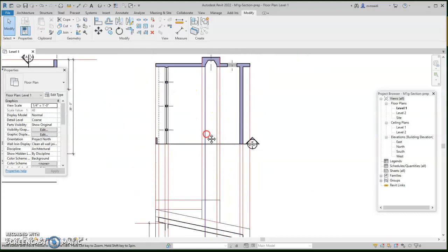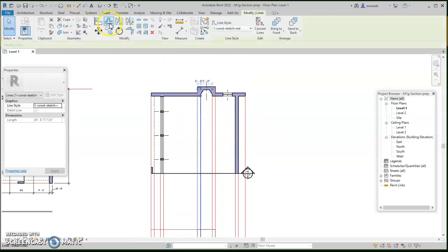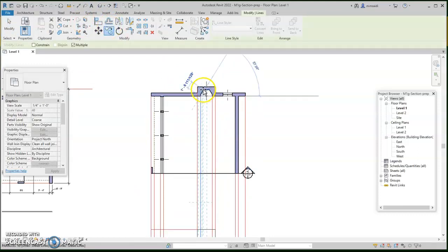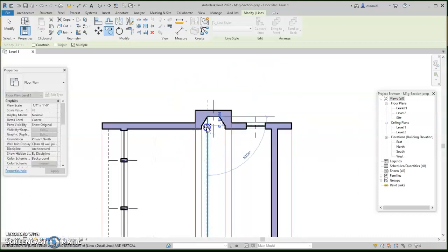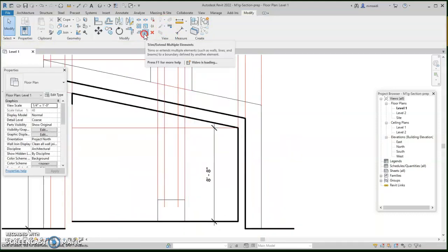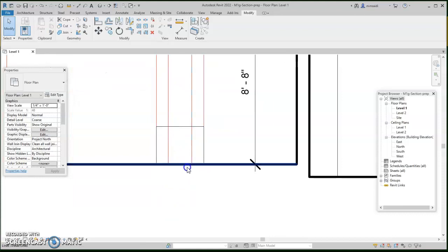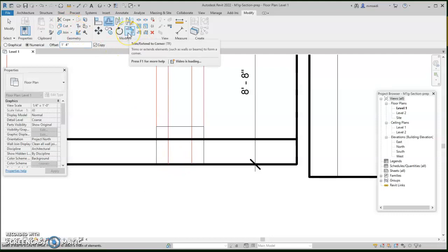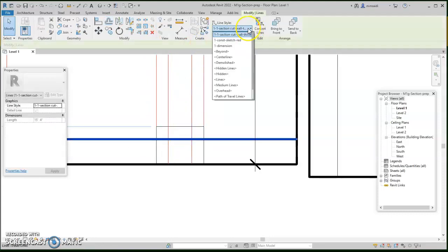Now I'm going to take another line, and I'm going to take this line, copy. From this junction, I'm going to go to this intersection. And might as well put it on the opposite intersection. That's the inside of my fireplace, and I would like it to go all the way down, extend to that edge and this edge. Now, that portion is 1'4", so I'm going to offset 1'4" here. And I'm going to quickly trim it if I want, but I'd rather not. So what I'm going to do is first place that into a thin line.